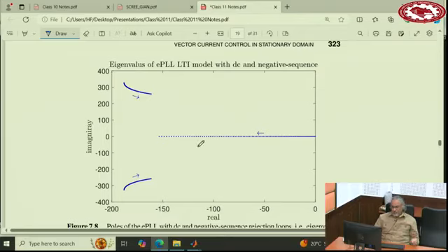My recommendation is to increase mu0 until all 6 poles have almost similar or equal real part. Then you will get some good responses. If you stop before that, you have some slow responses. If you stop after that, you may have faster responses but more oscillations. So this seems to be a good trade-off, but I cannot prove it.